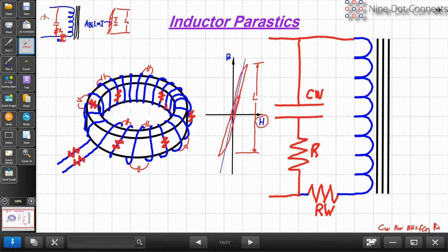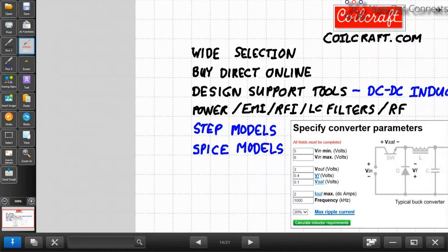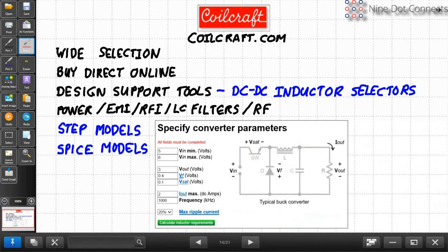At very, very high frequencies, you're going to measure the core loss. You can check, let's say you don't put any DC in, but you pump it at a very, very high frequency above its self-resonant frequency to where the capacitance dominates. In that case, you're going to be measuring all that loss in the core. Okay, so this is an ideal representation of a transformer, I'm sorry, of an inductor. And this is what we're going to look at very shortly. We'll see that the self-resonant frequency comes up over and over and over again.